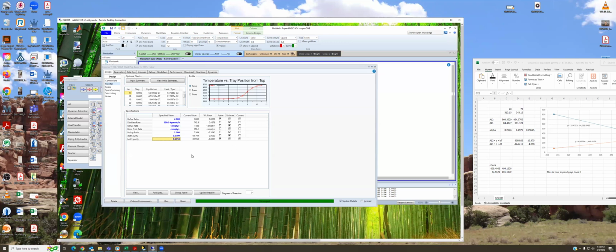Before we do, though, I want to point out one thing. It's a valuable process to specify purities when you're trying to get a simulation to converge. But when you're operating a real column in the real world, you don't operate off of purity spec. You change flow rates by opening and closing valves.